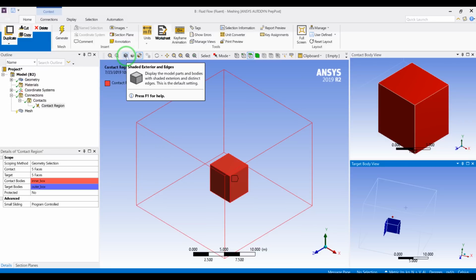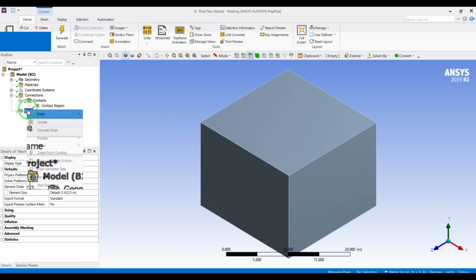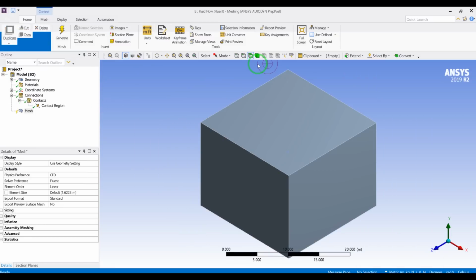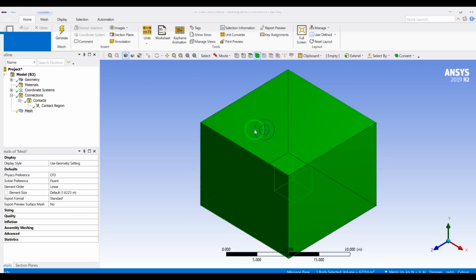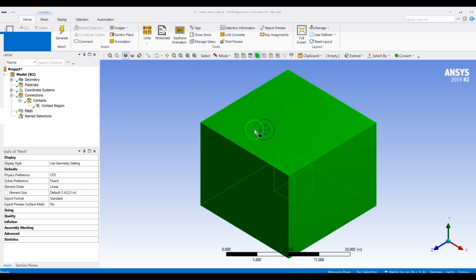Here it is selected by the ANSYS meshing and defined as an interface or contact region. So this is mostly the same method as in Mechanical, because ANSYS meshing shares the meshing inside ANSYS Mechanical. This is the more common way of defining the contacts in ANSYS Mechanical. So here we select the outer box and F9 to hide this.